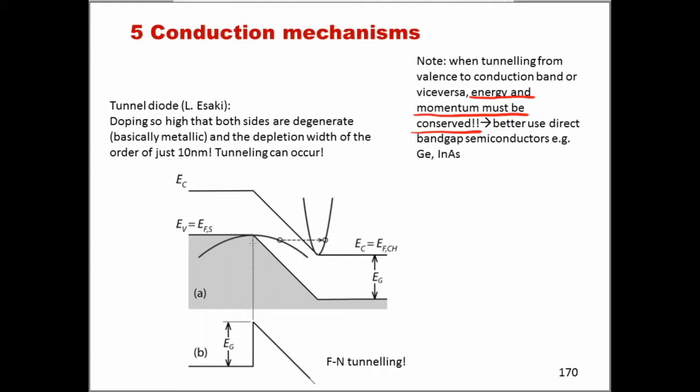Also, one question we should ask ourselves is: the electrons that tunnel from here into the conduction band of the N side, what barrier do they see in front of them? Well, the answer is relatively simple here, because for those electrons to tunnel, they effectively have to find themselves in the conduction band, which means that the barrier these electrons are seeing is effectively this one here.